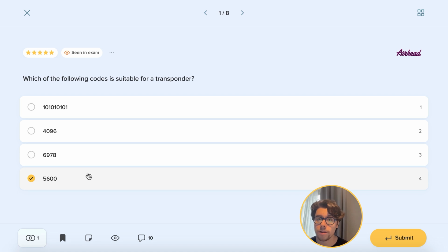They have altitude reports in increments of 25 feet, and actually these are the transponders that are required for TCAS to operate and in order to send resolution advisories to both aircraft if they are on intercepting courses. So this is the transponder that you need, and all the other information that you might hear from that ATC uses will be sent via the ADS-B or ADS-C. Just for your future reference, this is something that we could dive a bit deeper during the instrumentation subjects. However, remember that 4096 is all the combinations, and 5600 in this case will be the only correct code